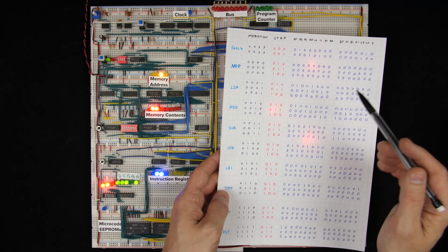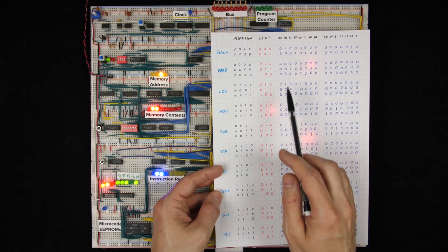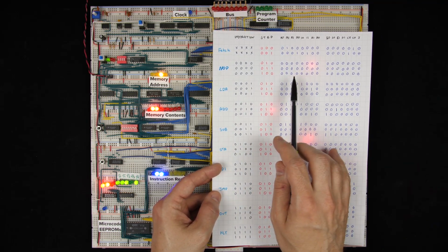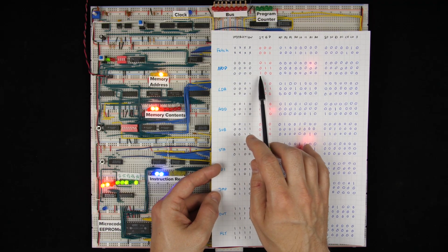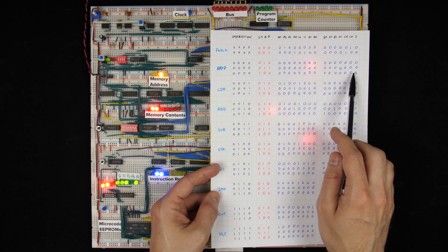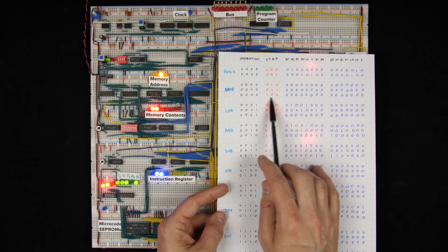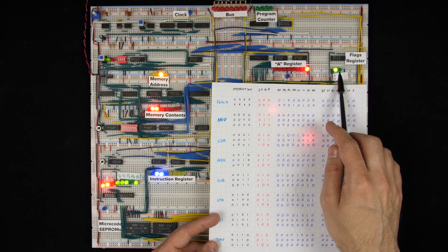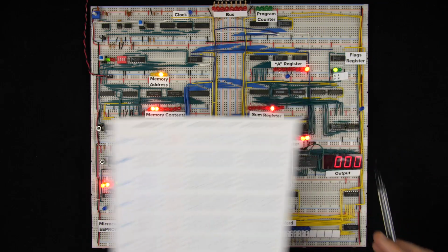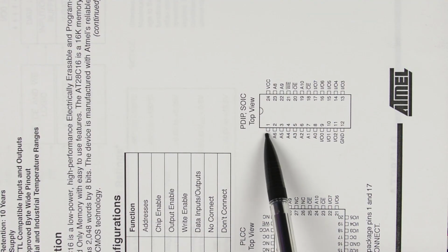So what we need to do is change the way that our microcode works. Instead of being a lookup table like it is now, that takes a 4-bit instruction and a 3-bit step and outputs a control word, we need it to be a lookup table that takes a 4-bit instruction, a 3-bit step, and the 2-bit flag register and outputs a control word. Luckily, the EPROMs we're using have 11 address lines, and we're only using 8 of them.